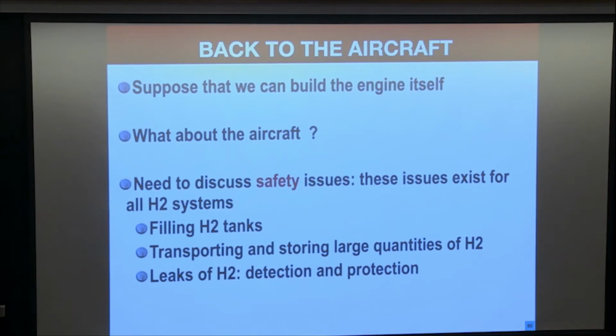I talked about the aircraft, but this is actually applicable to all H2 systems. What about safety? That's a big topic. Safety for H2 is an enormous question. If you talk about the aircraft, you get this 20K liquid H2 that you need to transport from a tank to the aircraft. If you think about a line in which you transport a 20K fluid, this line first must be cooled to 20K. Otherwise, you will have boiling everywhere.